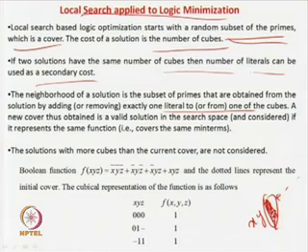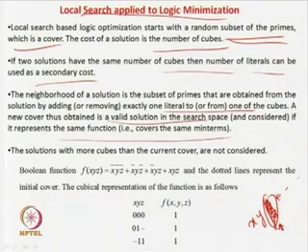So, what does it do? It will actually modify the function. So, you have to just check whether it still covers the function or not. If it still covers the function and is equivalent, then it is fine. If it remains equivalent and still covers the function, that means you have removed one literal and you have reduced the cost. So, you have to keep on doing it till you are satisfied with the cost of the function. Okay. So, the new cover obtained must be a valid solution and represent the same function, then it is considered, otherwise you have to replace this literal back and try with some other.